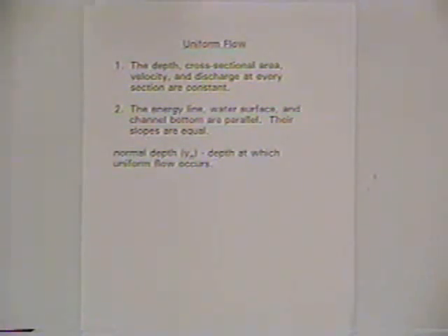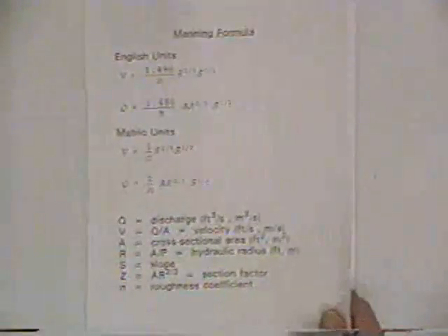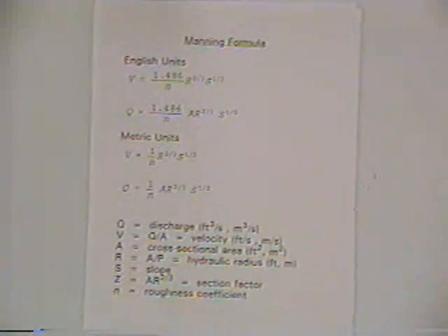And so we're planning for open channel flow problems on the exam to limit themselves where we recognize that this is a uniform flow problem. And so we can use the one equation that's provided in the reference handbook, and that's Manning's formula, to deal with flow situations as far as a uniform flow equation. Now, the energy equation's basic concepts are equally valid to uniform open channel flow as well as pipe flow.